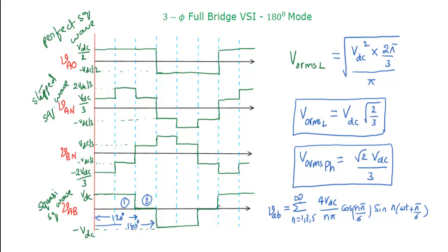So remember, another important thing we already discussed in rectifiers. In place of this one, we can use the sine also. When you're using sine, we need to take the pulse width. Pulse width is 120 degrees, 120 degrees divided by 2, 60. So then you can use sine n pi by 3. That also can be used in place of cos.